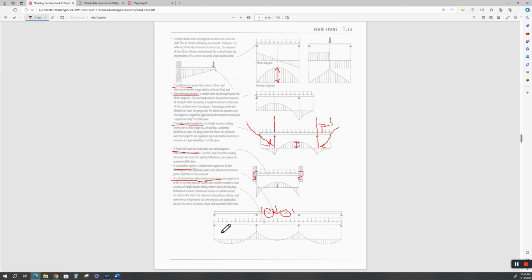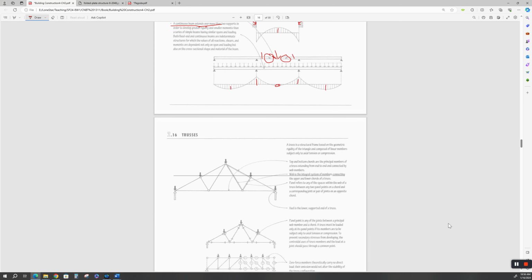All right, but if you made that one long concrete beam, then you can see how the moments are smaller than if it was fixed. And obviously right there in the center, it's really small, right? Because this is wanting to bend down and it's pulling this up. And this is bending down this way and it's kind of pulling that up. And that's a simple example.